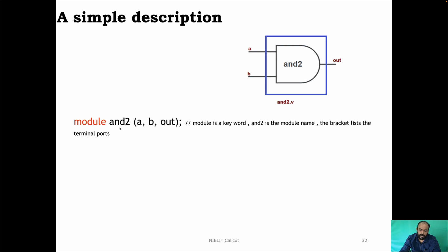The only constraint is that it should not start with a number or a special character, or be a standard keyword. So I have written here AND2. Make sure that you don't leave any space between AND and 2, because AND as such is a keyword. So you can write AND2 or whatever name, it could be even your name.